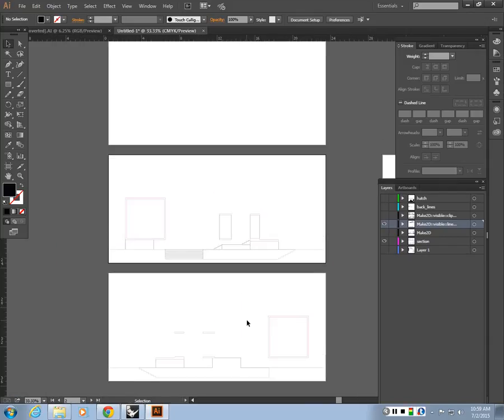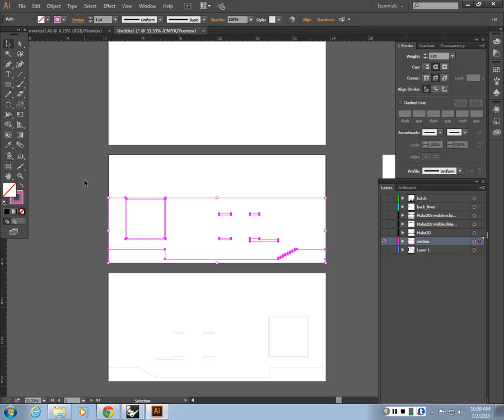The reason why I put them on a different layer is because I could use these objects directly for adding fills in Illustrator. There's a way to do that, and it's called the Paint Bucket tool. So what you do is first choose the objects you want to use for Paint Bucket, and then go to the Shape Builder tool, Live Paint Bucket, and then once you're in Live Paint Bucket, you want to click on the objects to activate them or to group them, so that you can